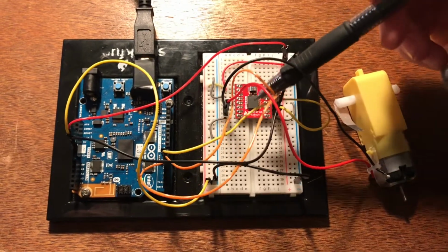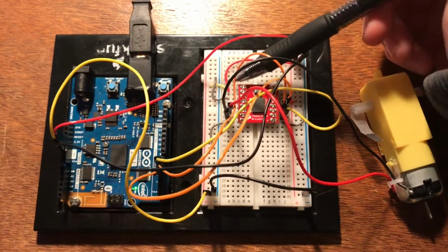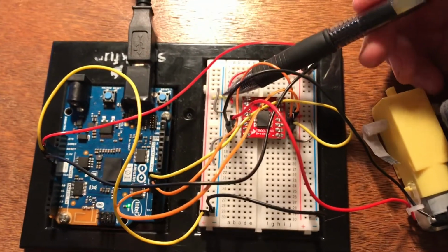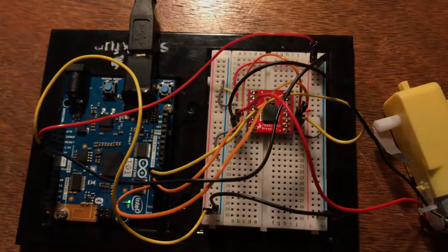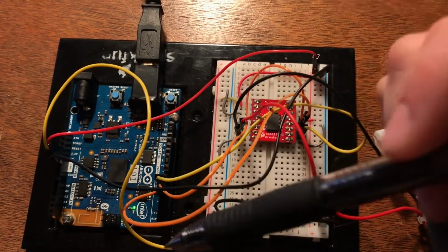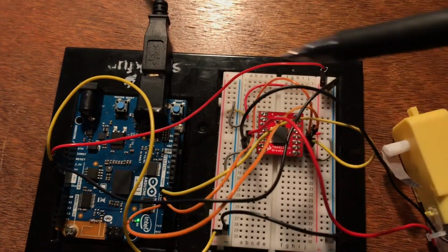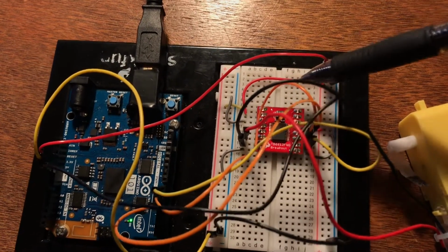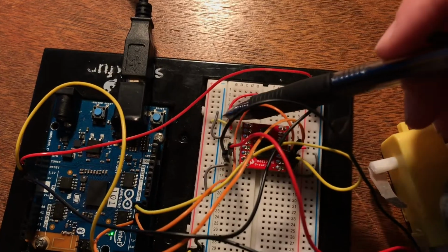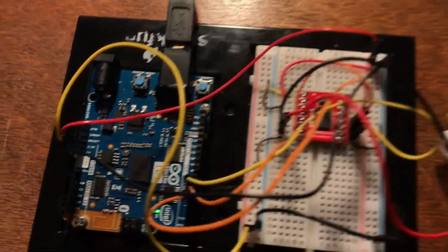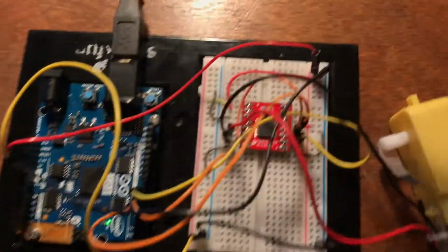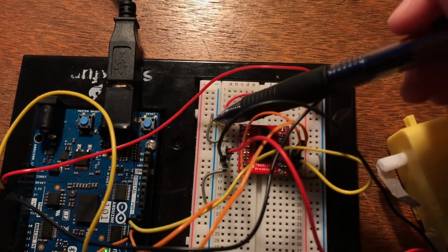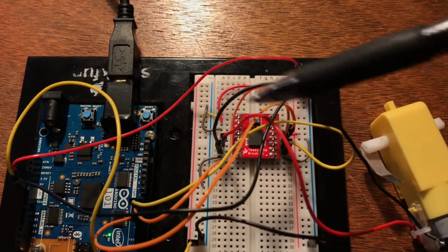So here we have the board, and we're going to have it attached to the 5.5 volts through this yellow wire here, onto the connection to the positive column here. Then we're going to have the board connecting to the 3.3 volts as well through this red wire here, and then this red wire here into the board at 3.3 volts. We're then going to ground the board by connecting it through this gray wire to the negative column, which is grounded by this black wire.